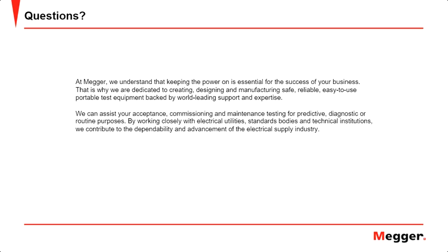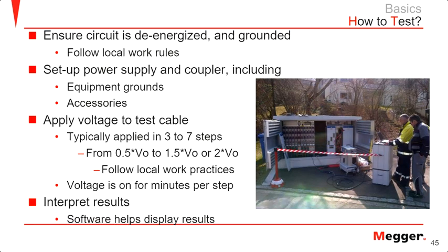Thanks, guys. I think we have time for one more question. So on slide 45, which instrument are we using there? We are using a TDM 4540 in that picture. It's a stackable unit. You have the bottom booster module, and I believe there's a 10 delta, VLF 45 sitting on top of that unit. And you have your PD coupler connected here, and then it's going to the cable itself.